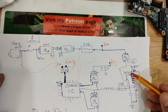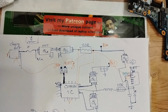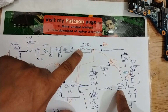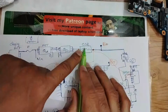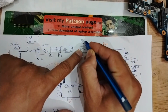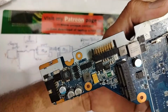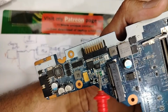Also, next to the battery connector, we have a CSR. I can even show you, my friends, these two current sense resistors in the motherboard. Sometimes we find R010 or R020. Let's see the motherboard, guys. You see, my friends? Let's take this one, for example. Here we have the current sense resistor. We have the second one.